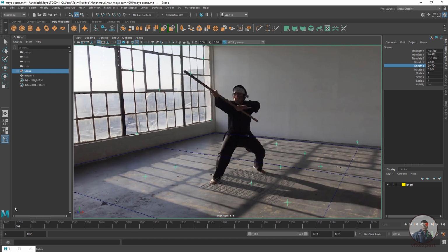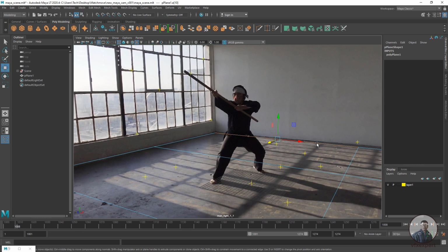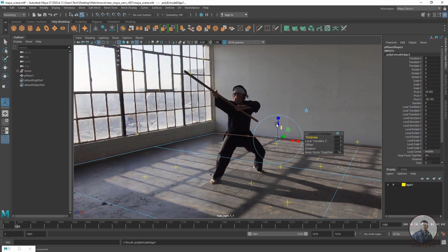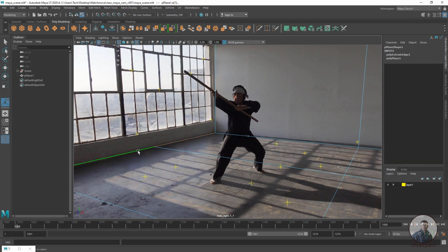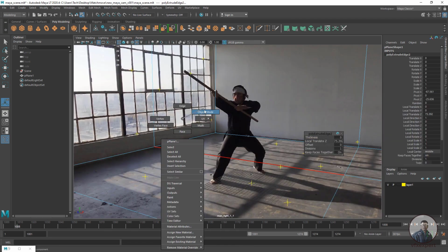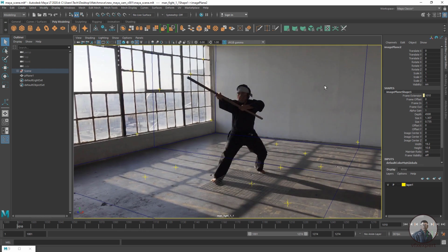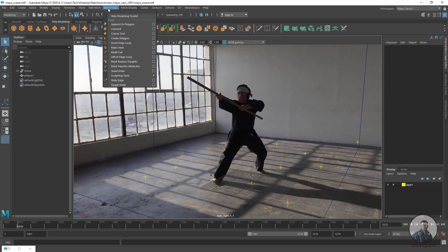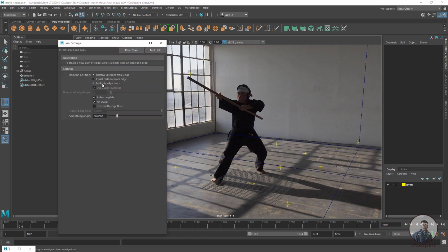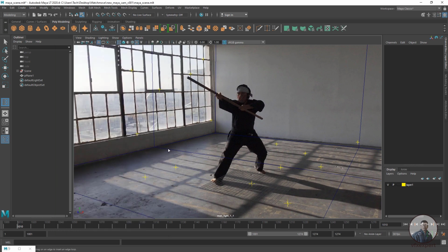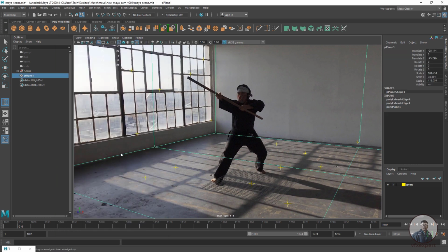So maybe after this, if you want to create this wall and this wall, then you can right click, select these two edges and extrude all these things here to object mode. Now suppose you also want to add some edges, simply go to the edge tool and take Insert Edge Loop, multiple edges, define 2 and close this one. Now simply we can click.